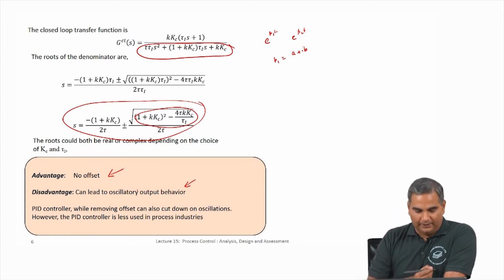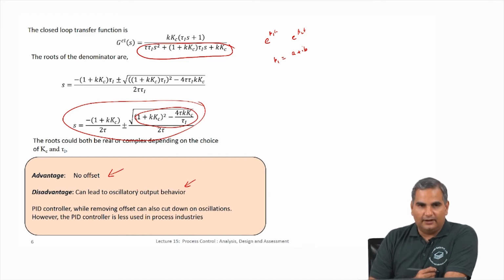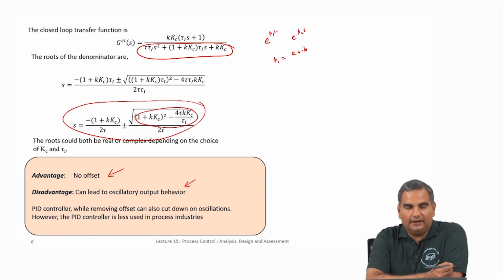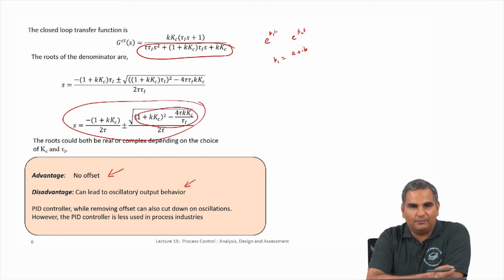Now, we talked about P and PI. The third type of controller is the PID controller. Most often you will see in industrial processes either P or PI controllers being used. For systems where you are looking at getting a very fast response, ease of implementation of a controller, and you really do not care so much about offset, you would implement a P controller.